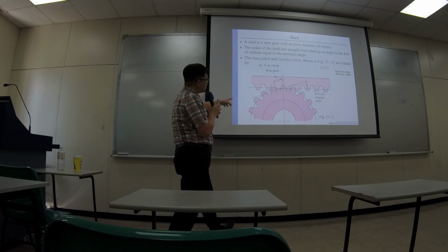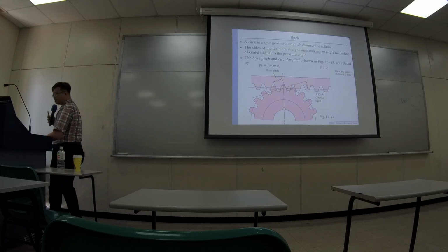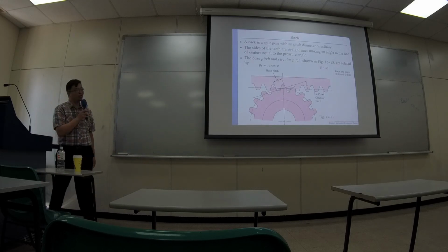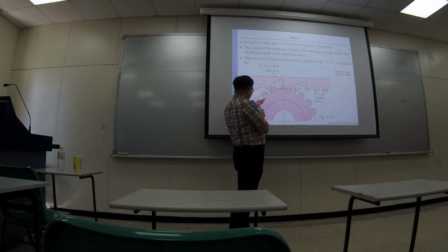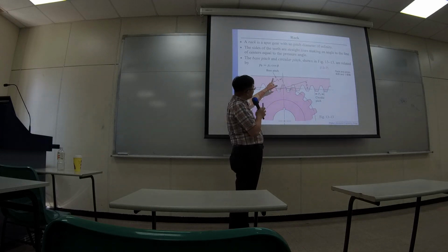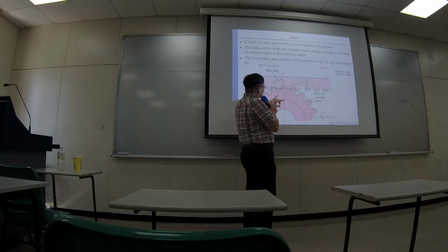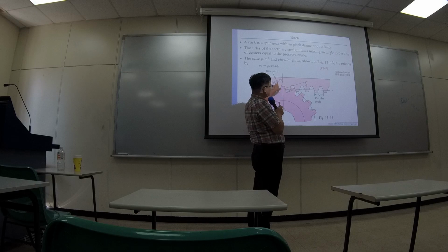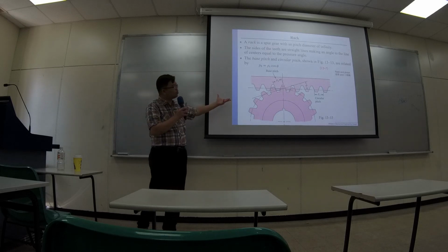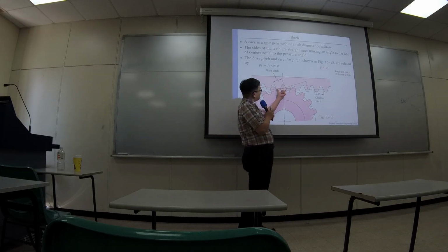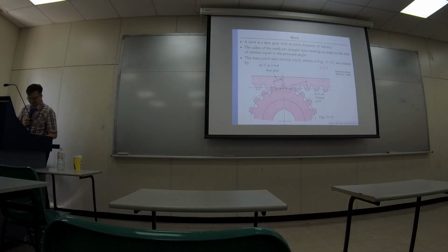Because this line is tangent to the base circle, I think. Yes, tangent to the base circle. But I didn't cover what the base circle is, so forget about it. Just know there's a circle tangent to it, and that's called the base circle. So this one is called base pitch because it's a different way to observe the pitch of a rack in a different direction. Okay, because those dimensions are important. You need to know the distance between one tooth and the other one, so you don't make an incorrect gear.